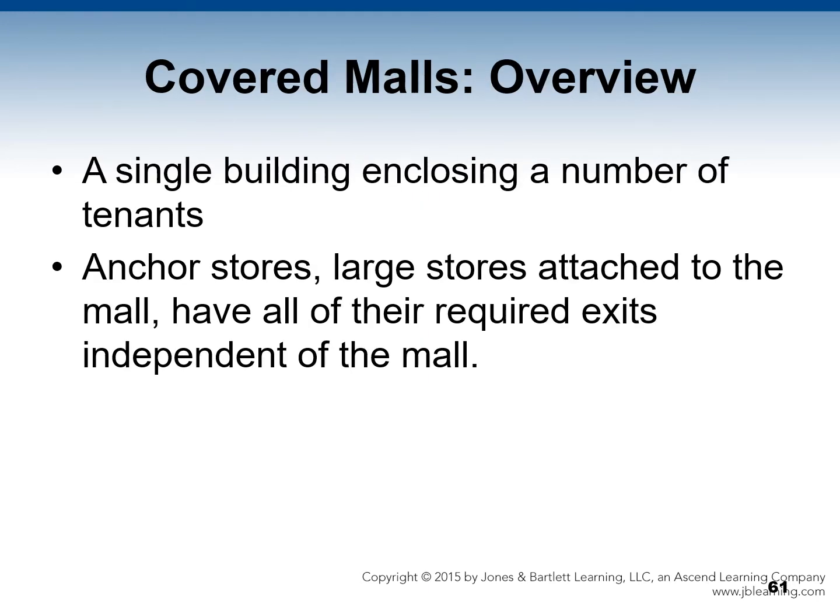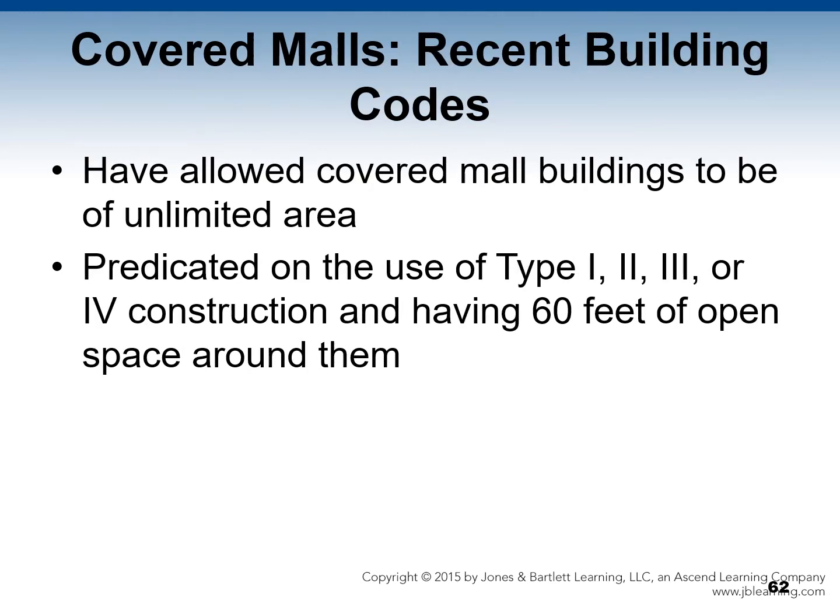Now there is the structure known as a covered mall. Covered mall buildings are a single building enclosing a number of tenants. Anchor stores, large stores attached to the mall, have all of their required exits independent of the mall itself. There are some recent building codes relating to covered malls. These recent building codes have allowed covered mall buildings to be of an unlimited area.